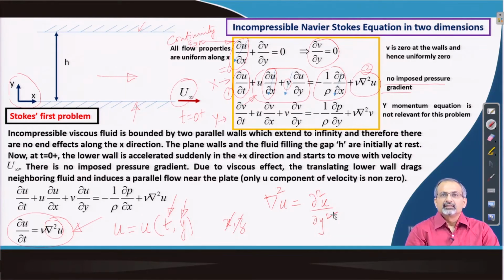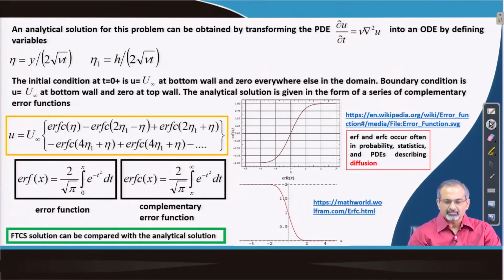So, this equation and the unsteady heat conduction equation are very similar to each other. This equation would be relevant whenever we are looking at the Stokes First problem, where u essentially means the x component of the velocity, while the unsteady heat conduction would help us solve for the heat conduction through a conducting medium as a function of time and space. We are interested to know whether we could look for an analytical solution for this problem.